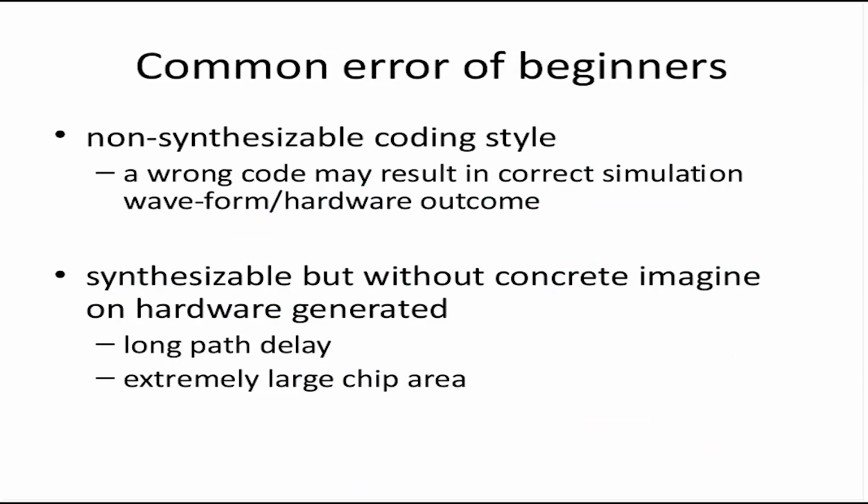The common errors which beginners make when they start coding for synthesis is that they might use a non-synthesizable coding style. Wrong code will result in correct simulation, but the hardware will not be correct, or the tool will not recognize those non-synthesizable coding functions.